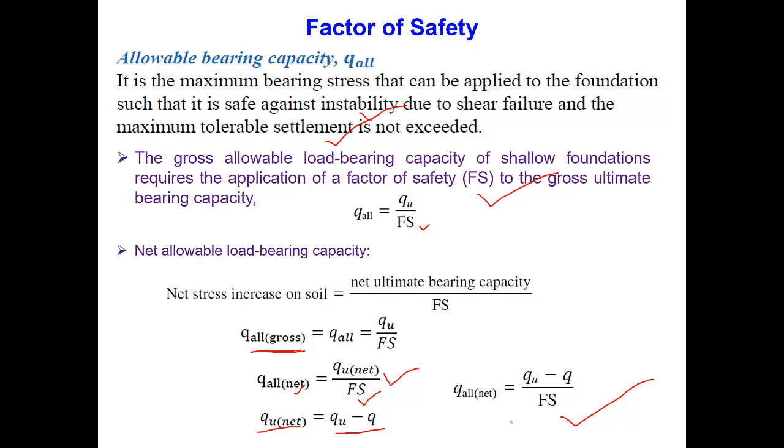Okay, so whenever you are considering the capacity with the surcharge soil, you are having less capacity of the soil, a little bit less, right? Because you added the load of the surcharge, but technically you are reducing the stress of the surcharge from the capacity. Do you get this information clearly?